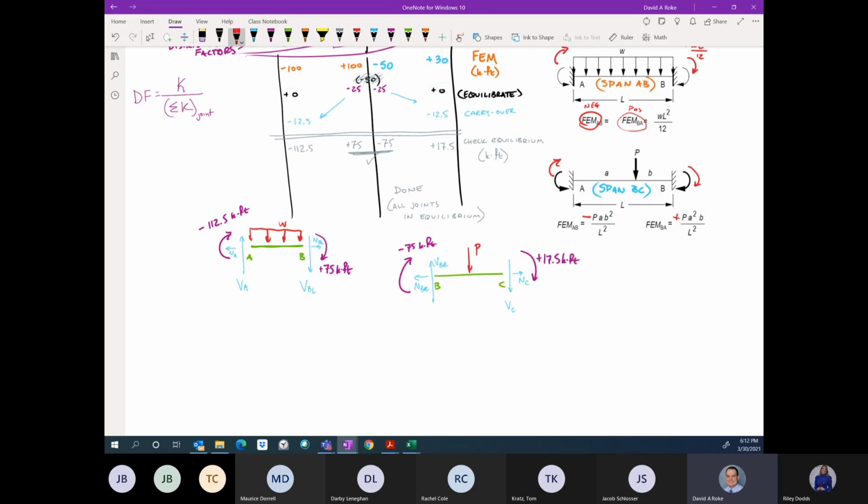so I don't anticipate it going into this grade of detail, but if you draw a free body diagram of joint B, you're actually able to solve for this reaction. So here's my reaction BY, and I have my internal shears VBR and VBL. I have my normal forces NBL, NBR, and I have my moments, which, now that I'm drawing the joint, I should be showing counterclockwise.